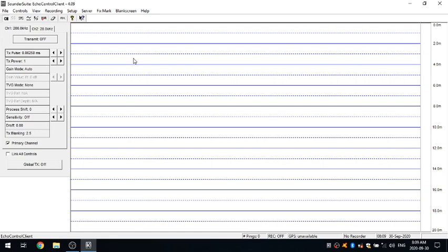Your TX power is next. There are 4 TX power settings that you have an option for. So typically with most of the Sounder series systems, you can get up to 1,000 watts of output power per channel, depending on the transducer, of course. The 4 power settings are kind of broken up into quarters. It's not quite 250 watts, 500, 750, and 1,000, but it's pretty close. Again, for the majority of surveys in 100 meters or less, you're probably not going to have to go over maybe a power level of 1 or 2.